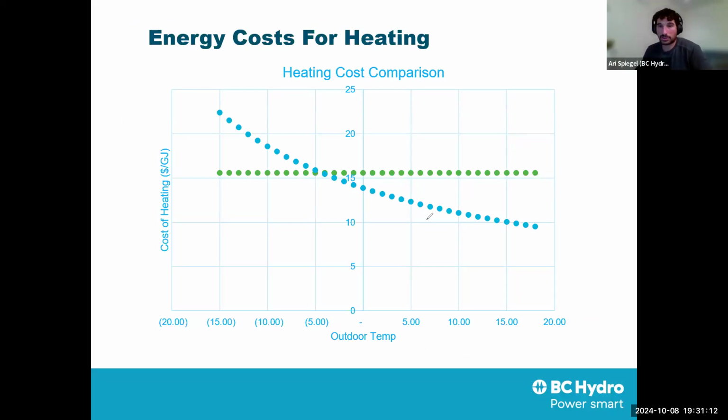So going back to our costs, if we're looking at ground source, for example, we would probably cut our graph here. A ground source would always be lower operating costs compared to a gas-fired system, and it would always maintain higher efficiency because it's not using a source temperature that gets any colder.